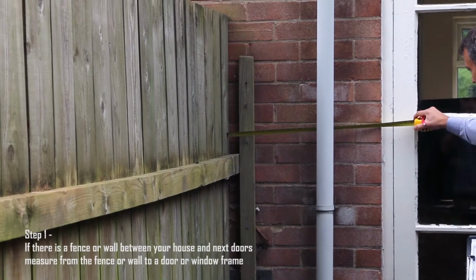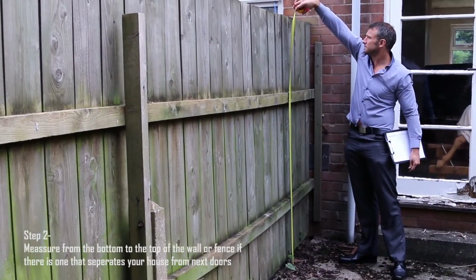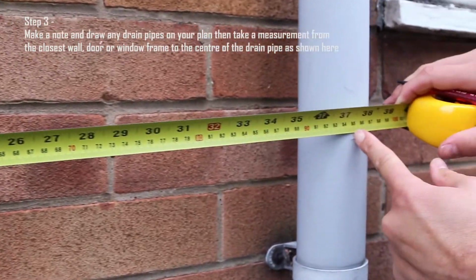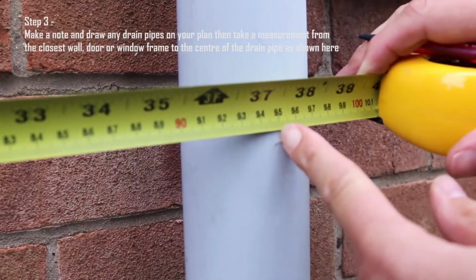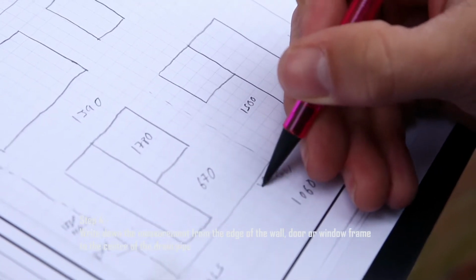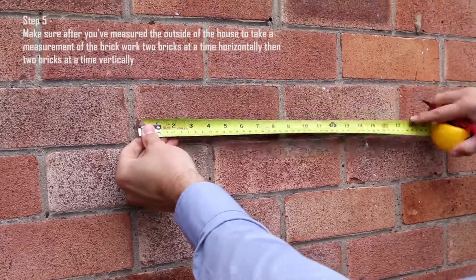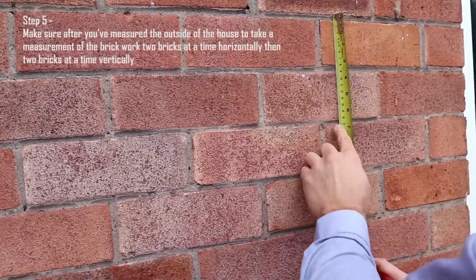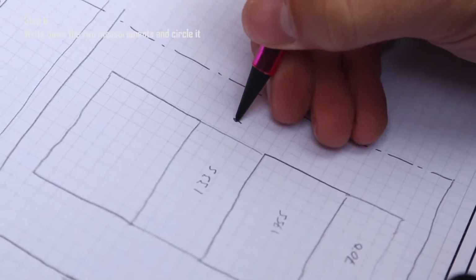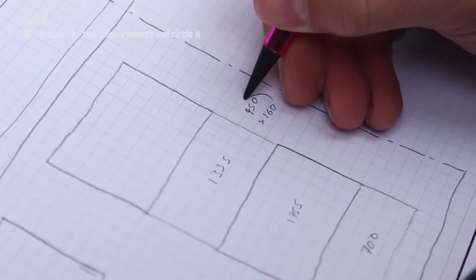References to boundaries and heights and drain pipes will be useful in designing. Reference to the centre point of down pipes and soil vent pipes. A reference of brick lengths and heights if necessary. We measure across end to end and over the top, 2 courses. Write clearly on the side of the elevation, 2 courses and 2 bricks.